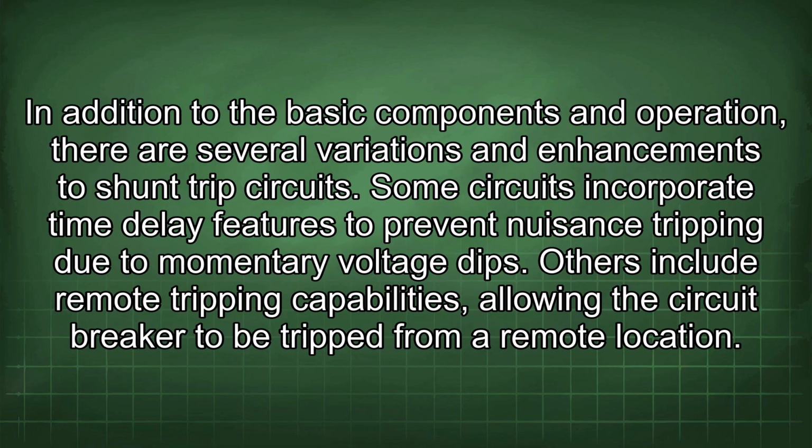In addition to the basic components and operation, there are several variations and enhancements to shunt trip circuits. Some circuits incorporate time delay features to prevent nuisance tripping due to momentary voltage dips.